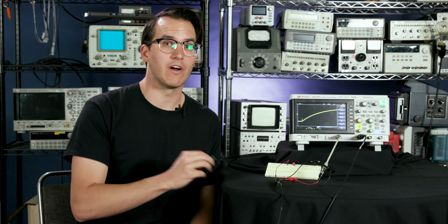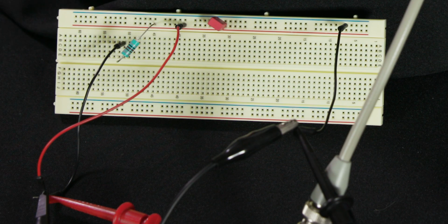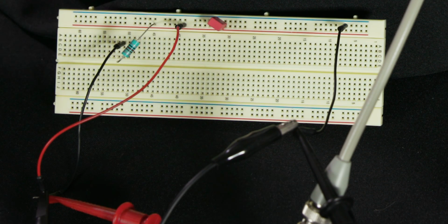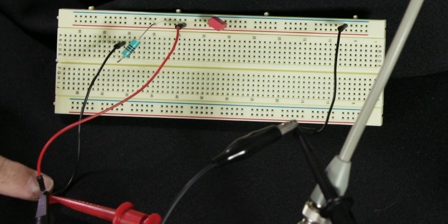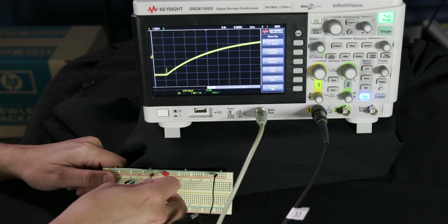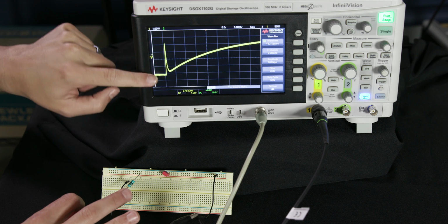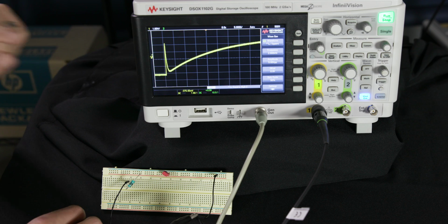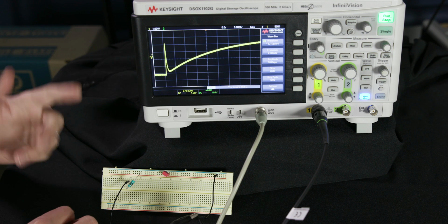And we can also make that glitch even bigger by adding our own inductor in series with our circuit. So I've added an inductor in series with our circuit here. The red wire is a bypass, so that's what we've been seeing on our circuit. The black wire puts that inductor in series. So as soon as I pull out the red wire, we can see a pretty significant spike from this extra inductance. So that shows that the spike is caused by inductance in series with our circuit.